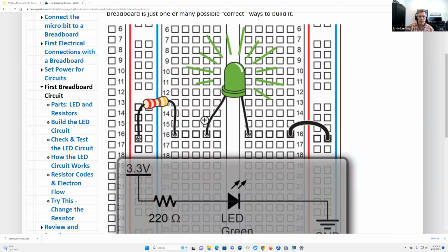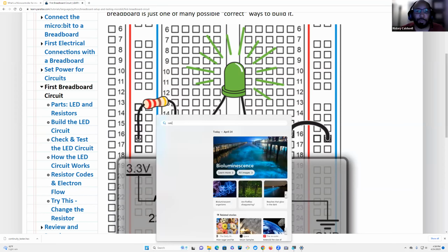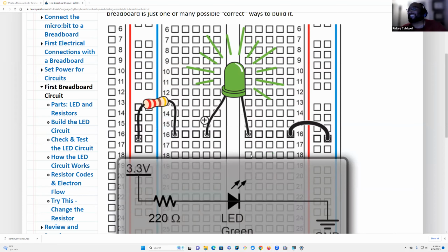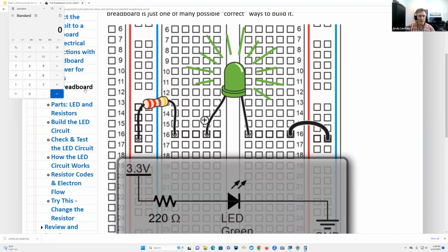But if you're connected to a microbit I/O pin and you're programmatically turning the light on and off, then you only get like 2.7 or 2.8 volts if you load it with a light like this. Then it's about 1 volt across here, so it's 1.8 volts across the resistor, and then we'll use V equals IR. Ohm's law, that's coming up soon.